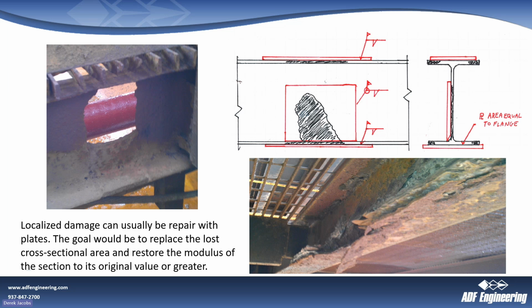And then typically too, we can do the same with the webs and weld those down. A lot of times that's welded. It can be bolted. Welding is much simpler, but sometimes environments at plants, welding is not allowed, so we have to figure that out. But we do want to try to restore that.